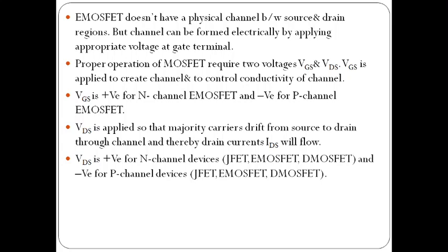It controls the connectivity of the channel. This VGS value is generally positive for n-channel enhancement MOSFETs, and negative for p-channel enhancement MOSFETs.